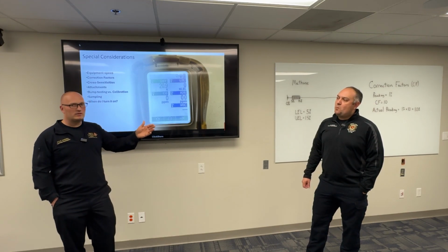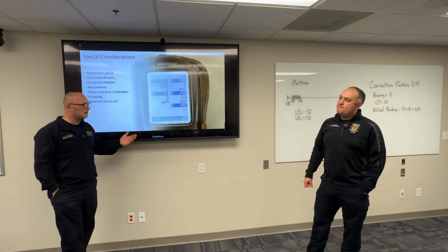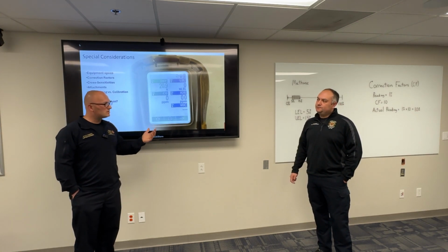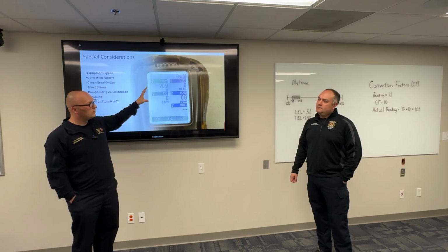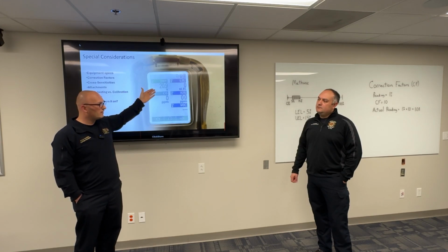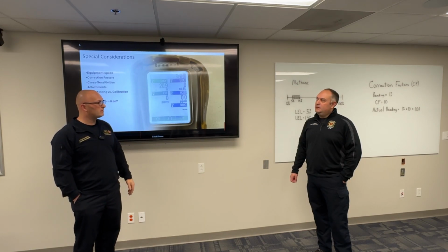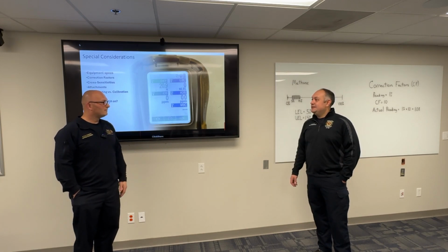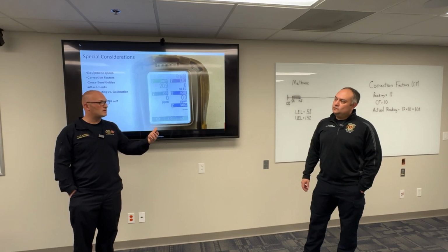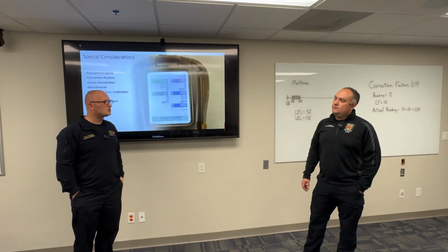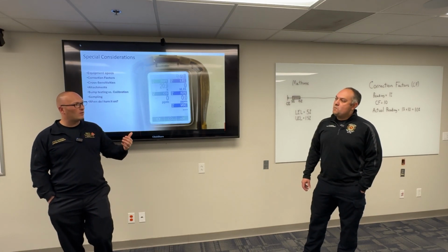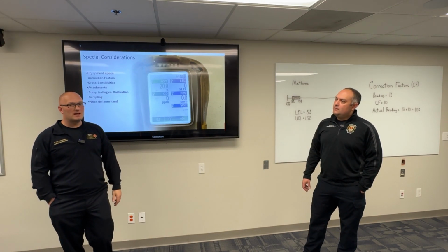Another thing to keep in mind, like we talked before about the whole Phoenix thing with the CO2 readings. That's something else to keep in mind when you're on some of these calls at gas stations and stuff like that. I might not have a CO2 sensor on my meter, but is there something else I might see a change on this meter for? Yeah, you could have oxygen displacement. So that simple one, if I walk in and just look at this, that's showing me I have something different in the air displacing that oxygen that I need to worry about or try to figure out what's going on. So these things are very important, knowing how they work and what I'm looking for as I'm going through all that.